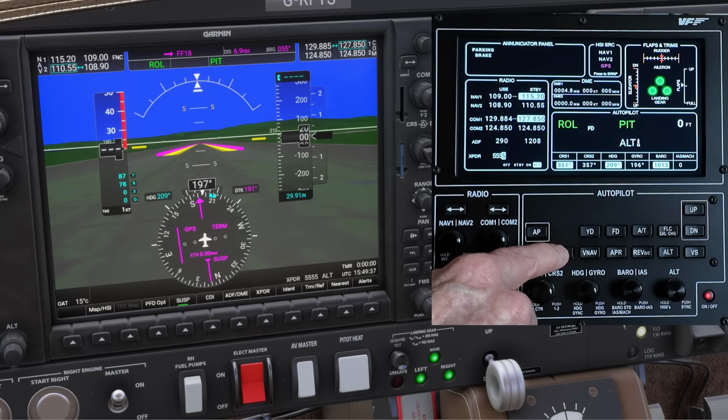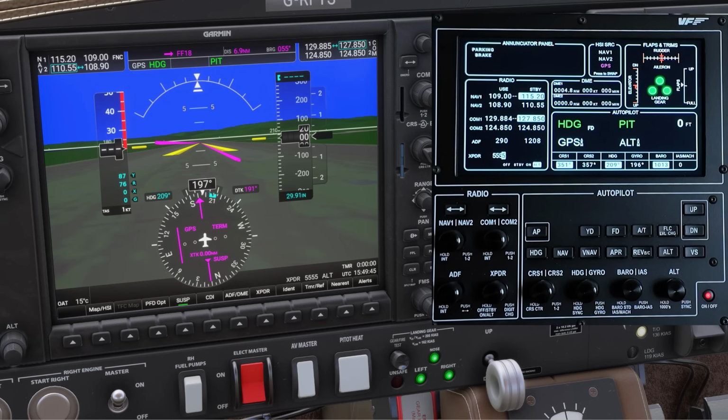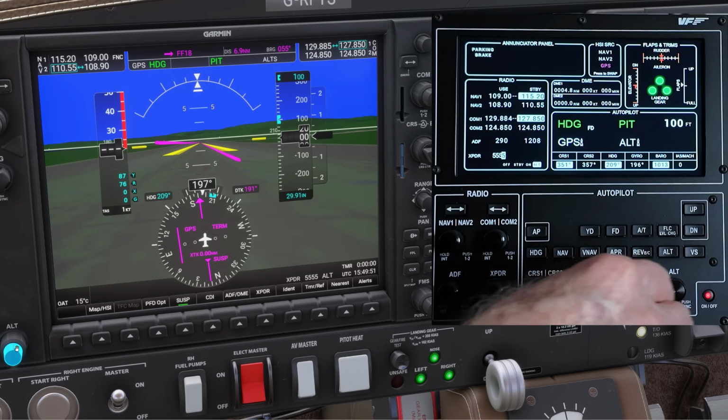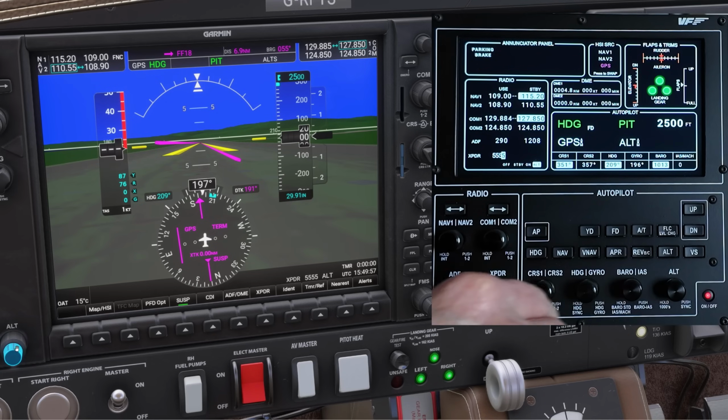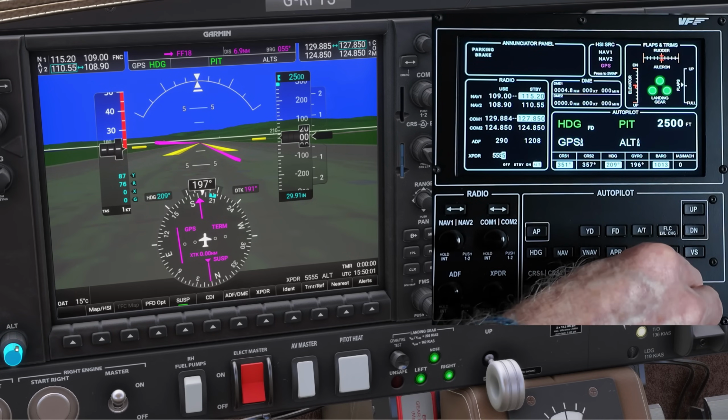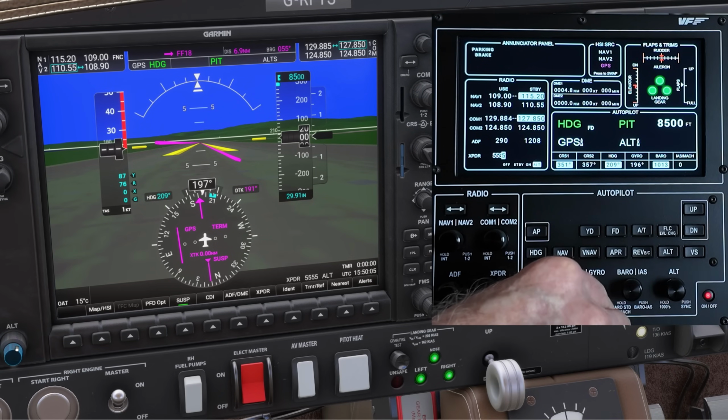I did come across one problem, and that was setting the altitude. Using the rotary on the Switcho was not recording on the PFD. Not sure if I was doing something wrong or hadn't synced. However, if I activated it in Sim, thereafter I found that the altitude knob worked exactly as expected. Rotate the dial to move up in hundreds and push it in to move it up in thousands, and thereafter it worked without fault. I have queried this with VirtualFly.